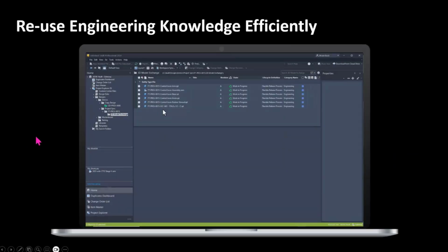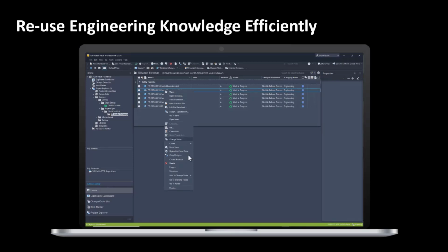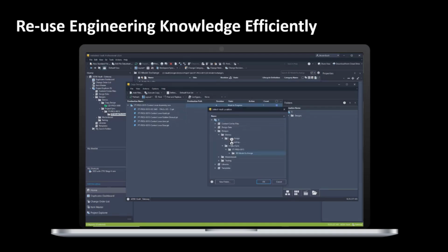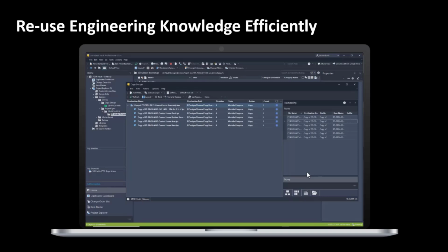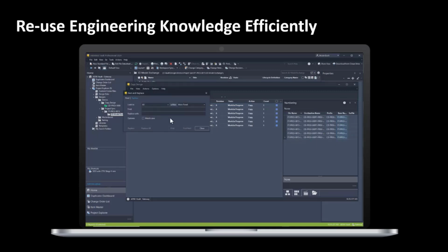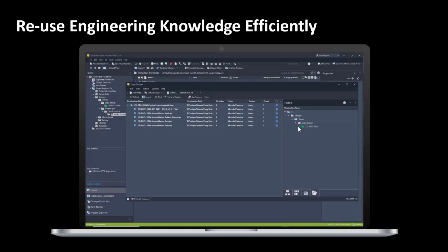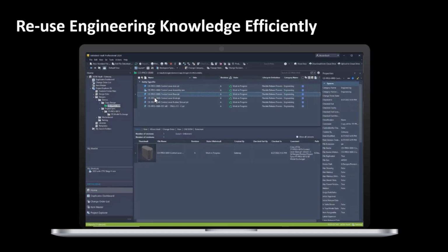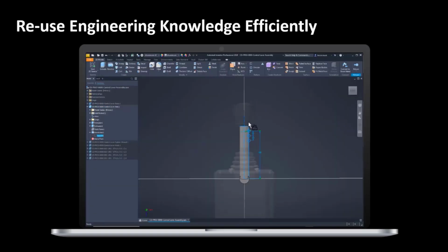Okay, so like in this example over here, I just want to copy this design. So this is one assembly. I can copy the whole branch, as we call it. So all the files, we can rename the prefix, change the prefix directly without going one by one. It's as simple as find and replace. Replace with what prefix and what suffix, so that we don't have to manually save as each and every file.